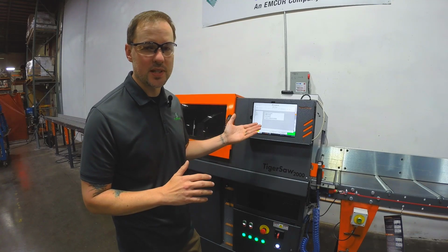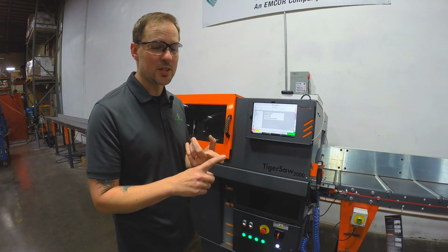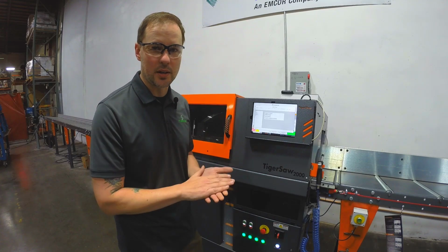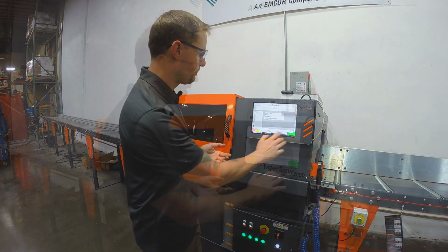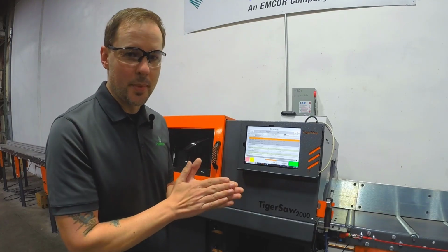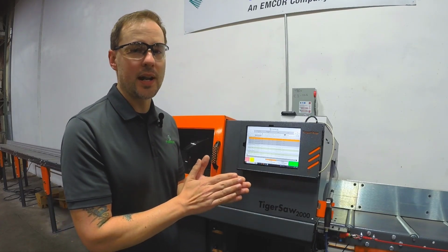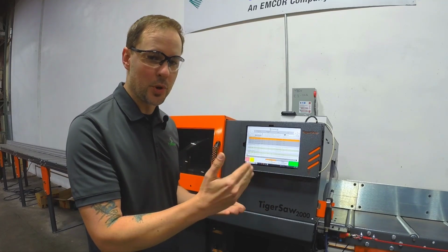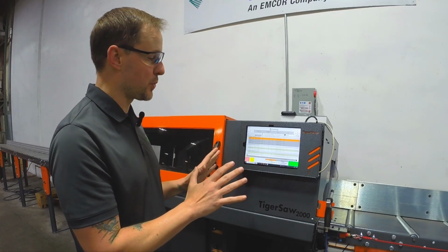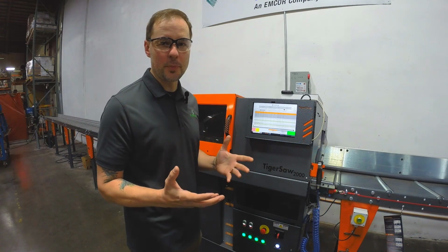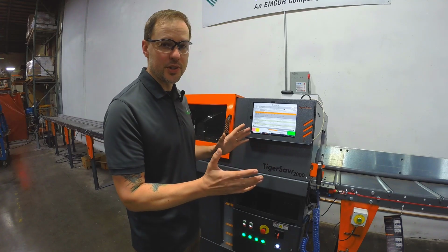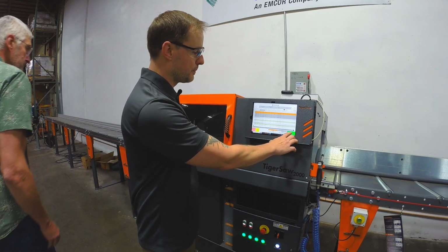You could create a specific template just for scrap labels that gives you the decimal length, because you'll need that later, and then maybe something that says return to stock. You can put it back on the rack for now. The rest of it's handled pretty much automatically. We have the machine configured right now to push the piece through, do a cut, and then automatically push without the user having to interact with the software anymore. So we've loaded the piece on and we've butted up against the positioner, and the operator at this point just needs to click the move button.